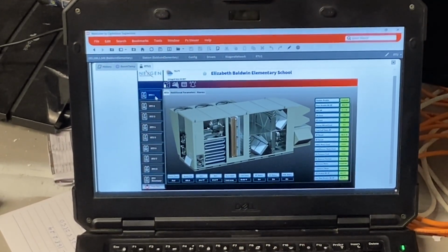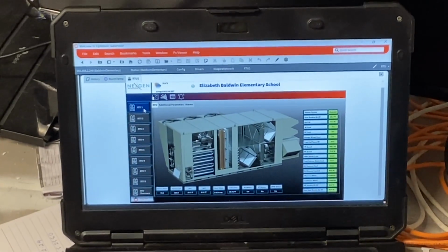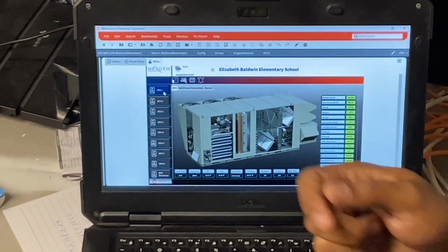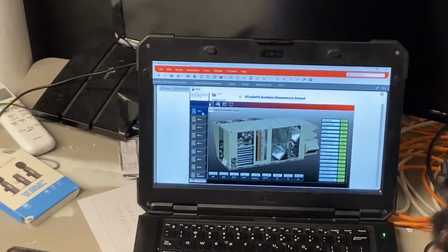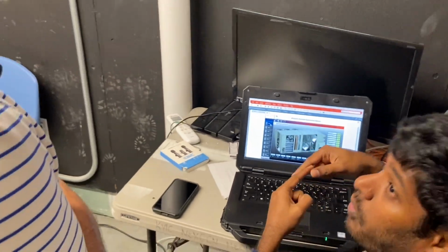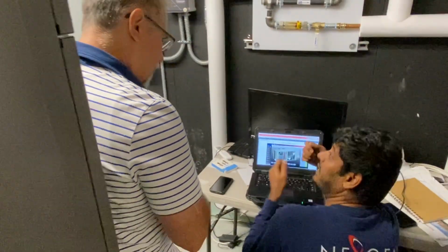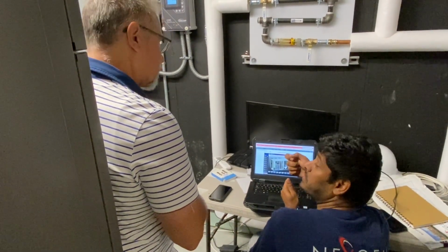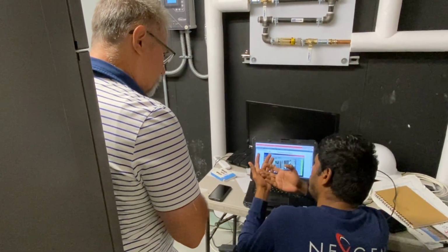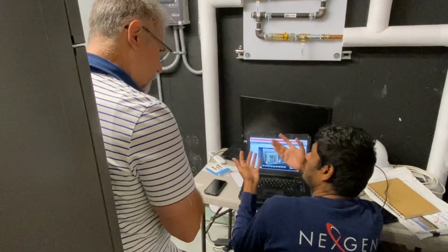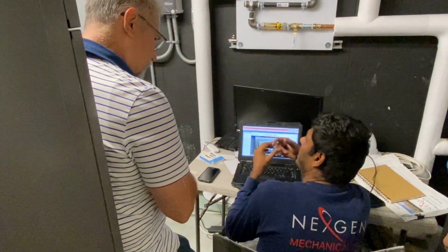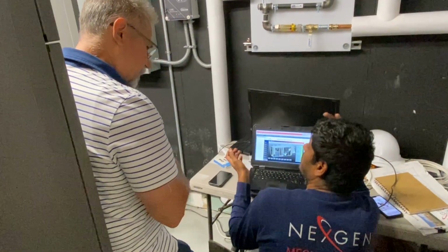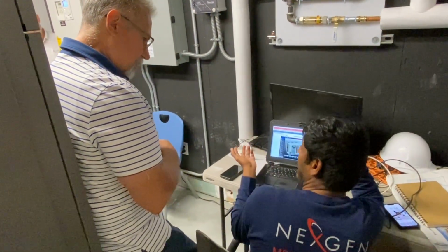During your cool down, if there is an economizer option available and the enthalpy is met, the economizer is going to override the cool down. So basically, two modes, cool down mode and warm up mode, and then the exhaust fan is going to track the outside air airflow.